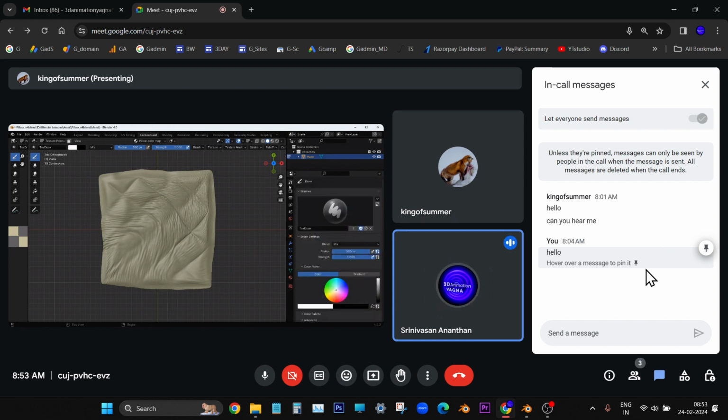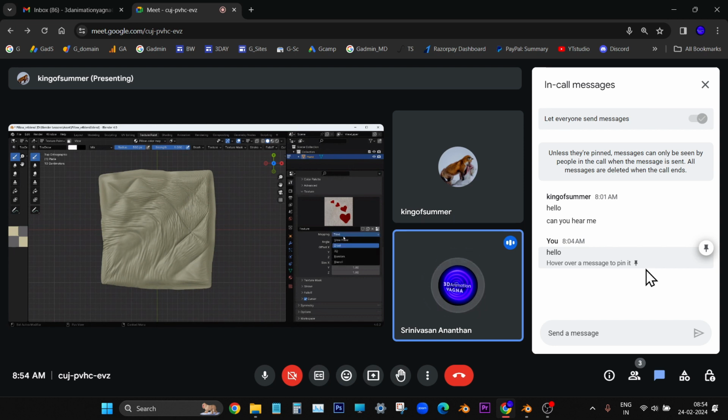Now you can go back to the tool settings, first icon in the properties panel. Yeah. Right. Now just scroll down. Now you will see the texture. Okay, fine. Now mapping method, just below the texture word, you will see mapping. There we have to choose stencil. Yeah, last one. Yes.